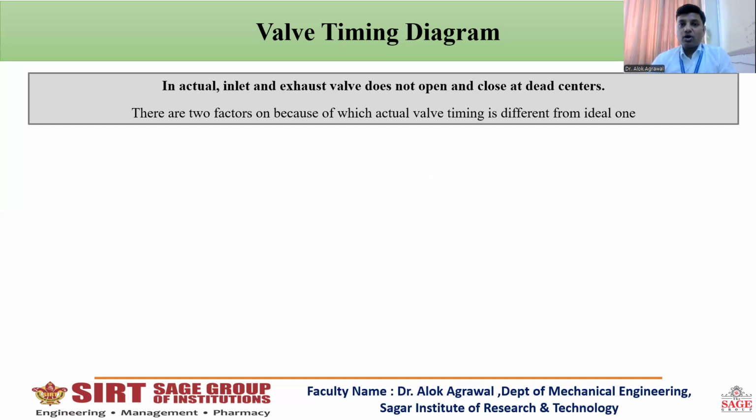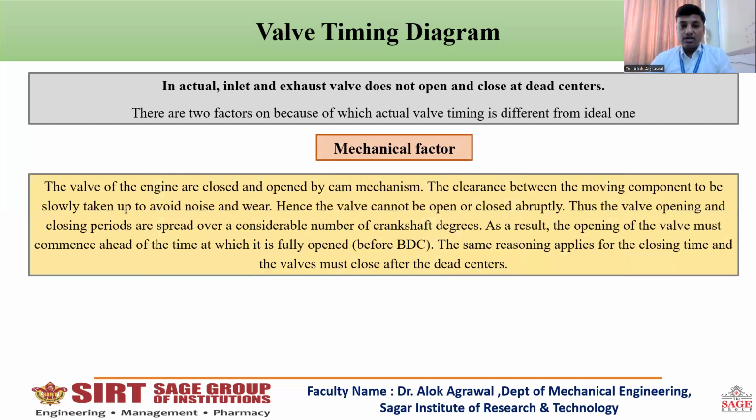It is because of two factors. One is the mechanical factor. What is there in the mechanical factor? In actual, there is a clearance between the valve and the mechanism which is opening and closing the valve. Opening and closing of the valve is taking place with the help of a cam mechanism.